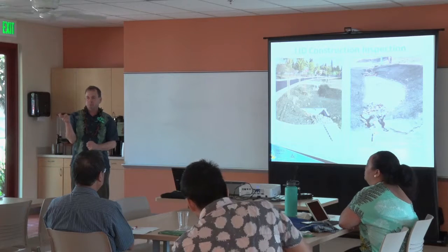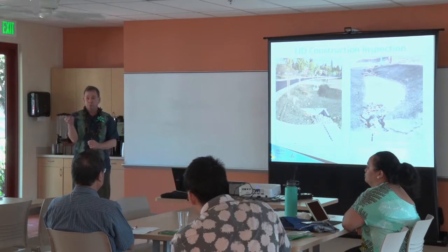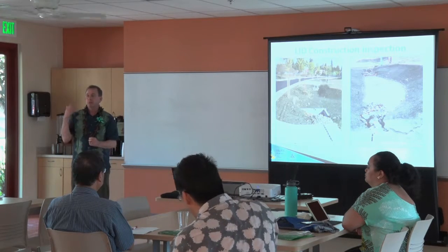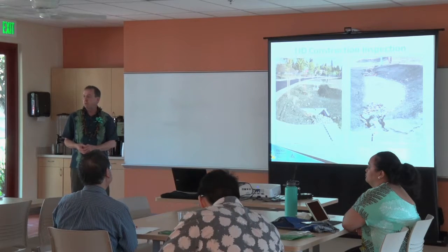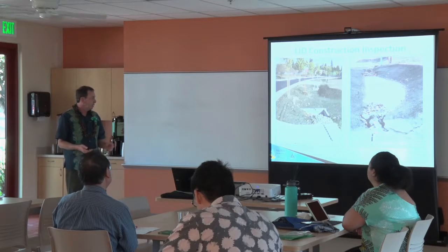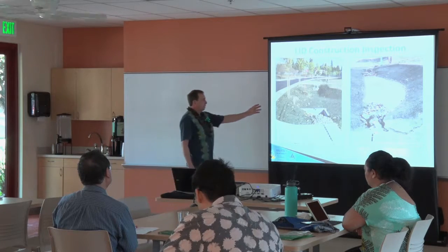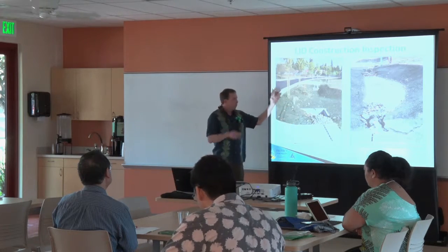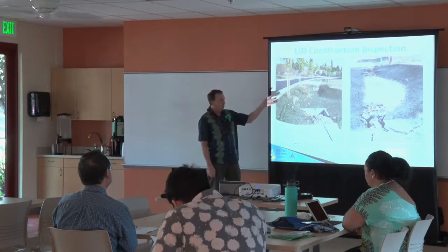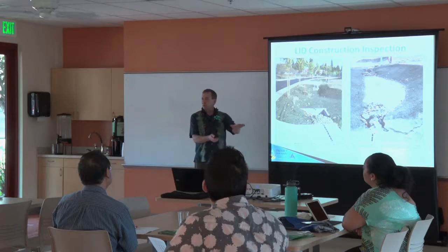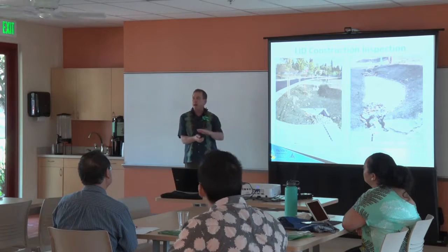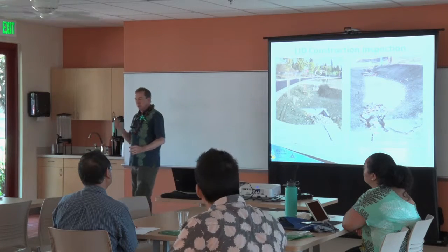construction. So you as the contractor, or you as a construction inspector, or as the owner, when you're out during construction, when we excavate this one and we've got nice uniform soil here, and we go down the road 3 blocks and we excavate another one, and we find out there's a distinct line and a different soil gradient there, that's a red flag.